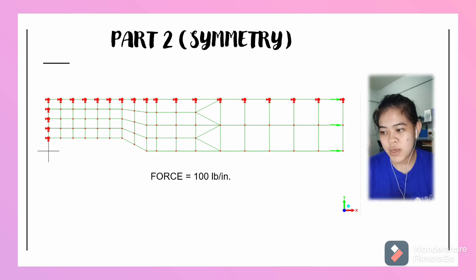The reason why it is meshed as such is that the aim is to have the transition from the smaller quadrilaterals to the larger quadrilaterals. That is why triangular elements are used at the center of the structure. These transitions are necessary because intermediate nodes along element edges are inconsistent with the energy formulations of the CST equations.